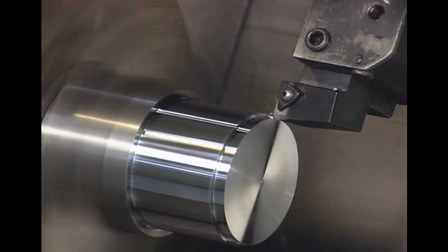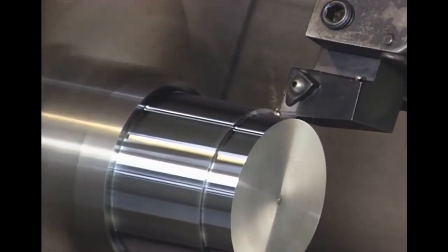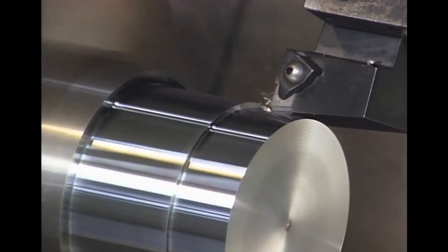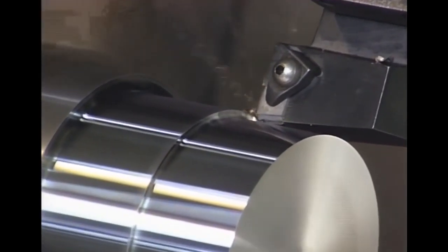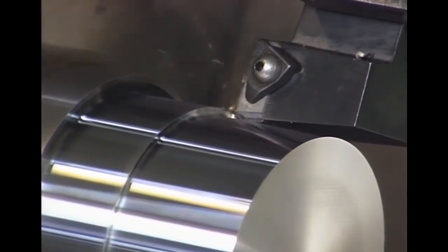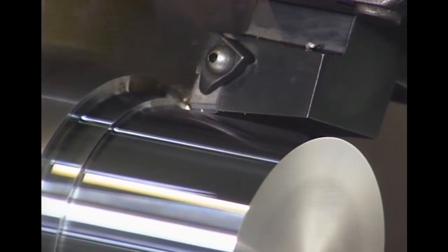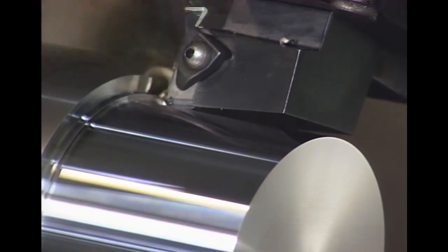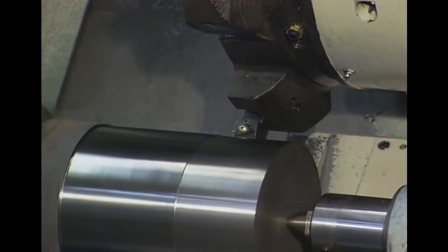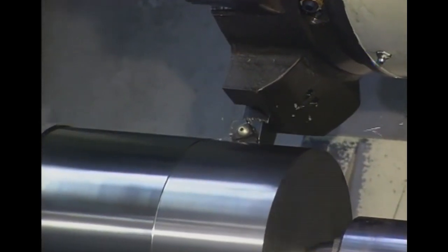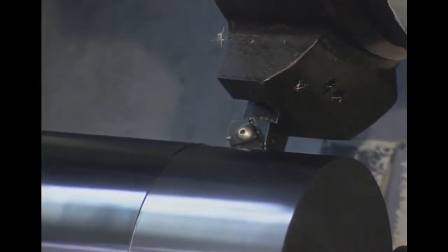Alumina-based ceramics are used for high-speed semi-finishing and finishing of ferrous and some non-ferrous materials. These tools are not good with aluminum because of an affinity between the materials. Alumina-based ceramics offer mechanical and chemical wear resistance, but lack toughness and thermal shock resistance. Thus, they are generally not used for milling, rough turning, or for interrupted cuts.